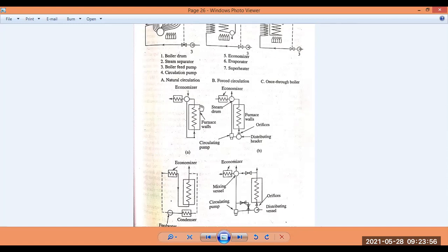The drum itself here enters the drum, and the headers are connected to the tubes itself. The water in the riser tubes is situated outside the furnace. Then the drum, or at the midpoint lengthwise, is situated outside the furnace. So the drum is not being heated by the mixture itself. These headers are connected to the water tubes that lie in the furnace wall and act as risers.